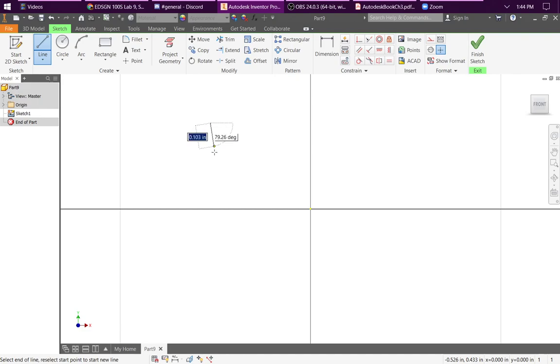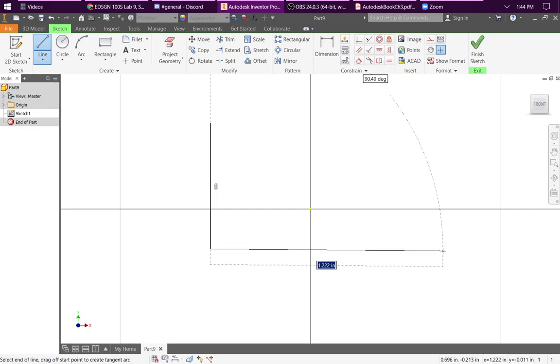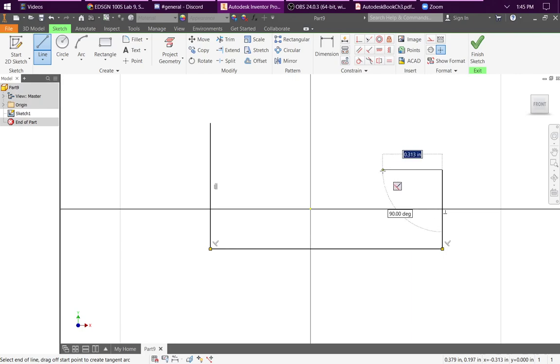And I'm going to draw out the shape first. Make sure when you're snapping that it shows you that you're getting your 90-degree differences between your sides here. I am not in any way worrying about the actual dimensions here, other than I do want this lined up with the top here. But other than that, I don't care about the dimensions because I'll add the dimensions in later.